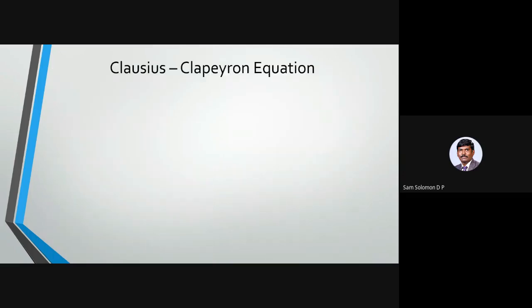The next one is Clausius Clapeyron equation. So sometimes this is also being asked, rarely, in 11-mark question also. Okay, but it is very simple. So this Clausius Clapeyron equation can be considered for phase change processes like vaporization, when you convert water into vapor, or when you convert a solid directly into vapor, that is sublimation, or melting. When you convert a solid into liquid, in all these phase change processes, this Clausius-Clapeyron equation can be used.